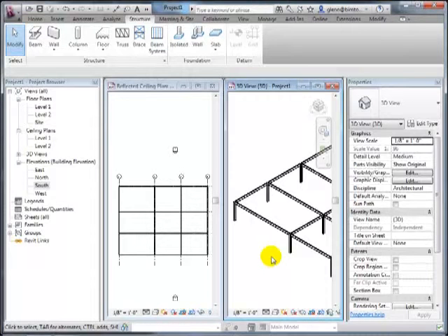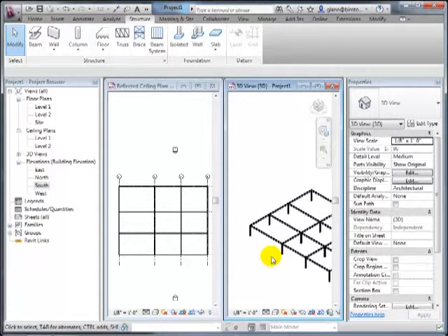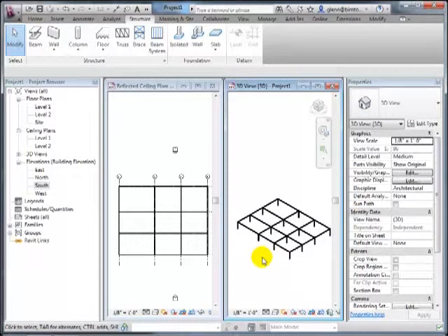When we do steel, what tends to happen is we'll put the floor in, and it'll be a lightweight concrete deck, with some sort of ridged pan underneath it supporting that concrete. And that whole assembly has a thickness of around 5 inches. So when we put in the beams for steel, we don't want to put them right at the floor level. The default one in here is 5 inches, but 7 inches would be for a thicker floor plate. So rather than just putting the beams in at the full floor level, what we can do, and this is what Rima was suggesting, is go through and do the offset.